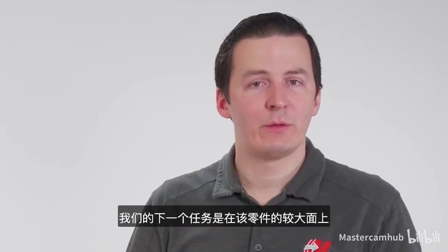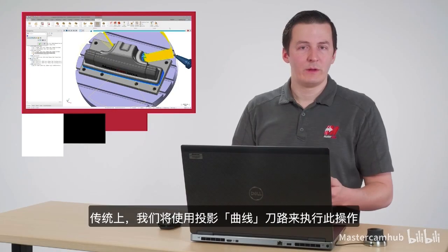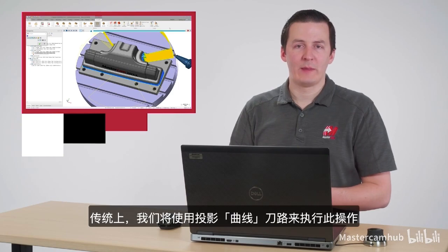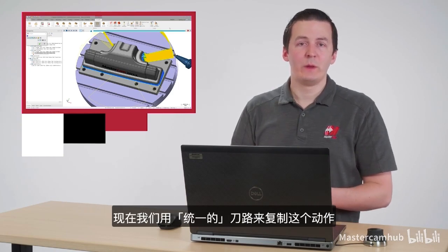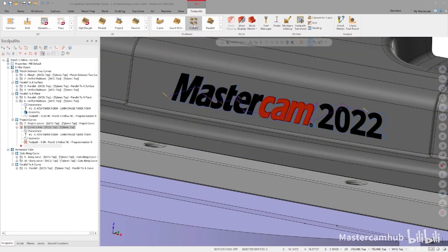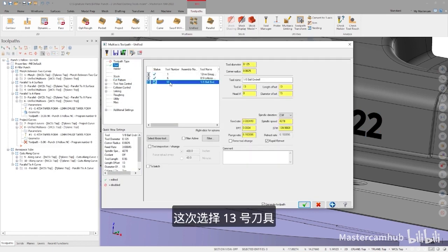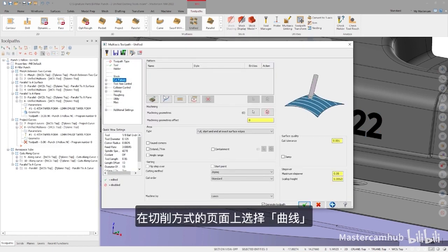Our next task is to trace the Mastercam 2022 logo on the large front face of this part. Traditionally, we do this with a Project Curve toolpath. Let's replicate this motion with a unified toolpath. This time, choose tool number 13. On the cut pattern page, select Curve.